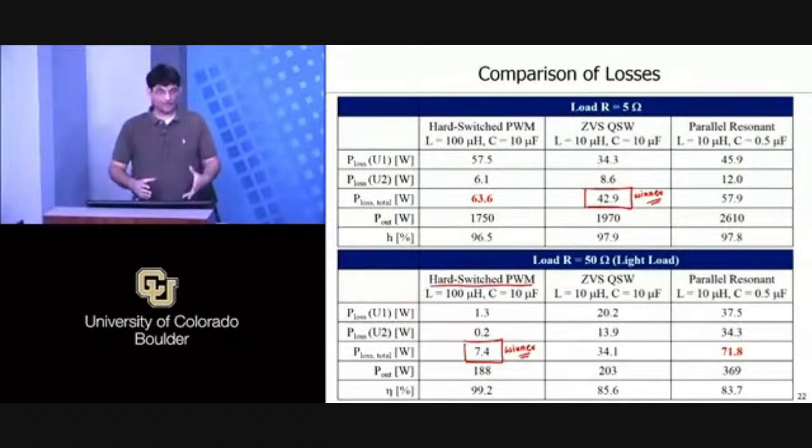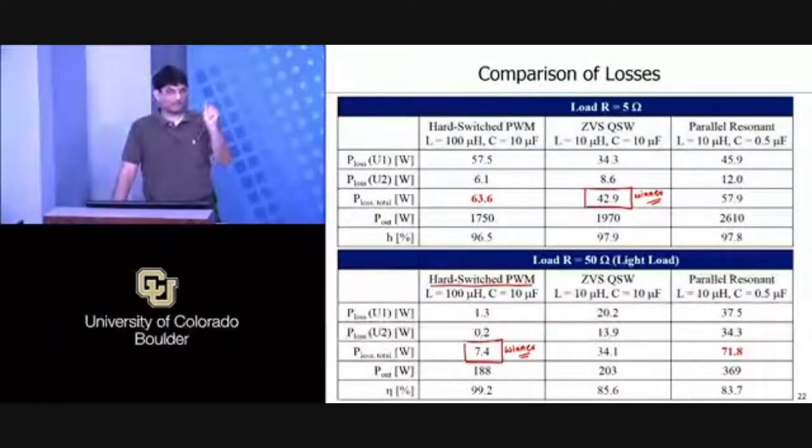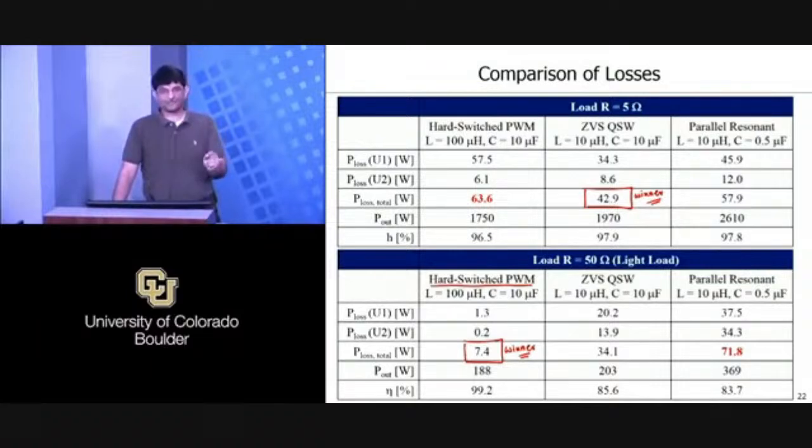But more importantly, it raises the point, which is a fundamental problem with soft switching converters, that you can design a soft switching or a resonant converter really well for one given operating point, but designing it to be highly efficient across a variety of operating points is the biggest challenge. And this course is going to teach you how to do that. So this serves as a motivation for, yes, we quickly were able to build a soft switching converter, but it isn't what we really want, and now we'll spend the rest of the course not just on this topology.